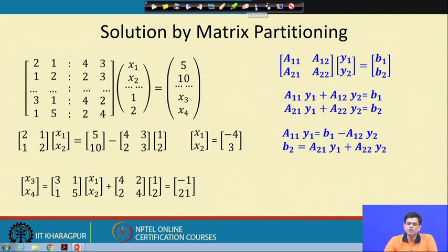This kind of situation we may observe in the matrix method. For instance, this matrix could be a stiffness matrix K, this is the delta vector, and this is the force vector. In such a situation we have partial delta known and partial F known. So, we need to first find the unknown deltas with the known F's, and then use that solution to find the unknown F's.